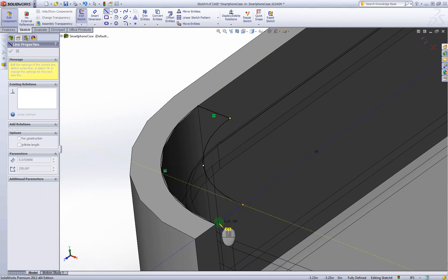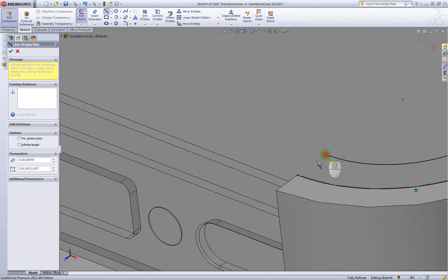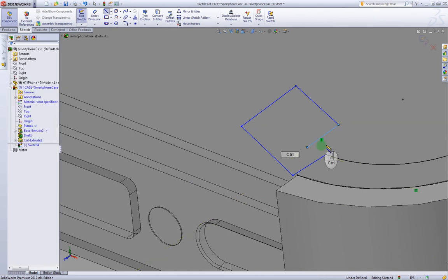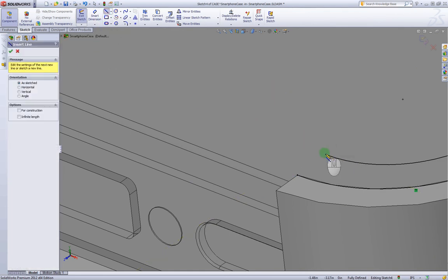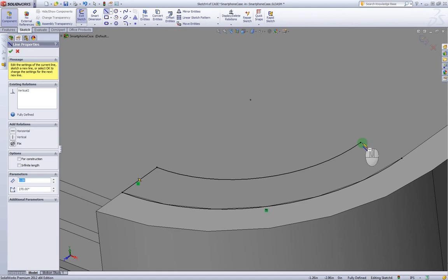Click once, click twice, and if you do it successfully, the line should turn off, meaning if you do it wrong, it's going to want you to keep making lines. I'm going to Control Z here, and if you do it right, you start your line and then you end your line, it just turns off. It's like an auto off because it thinks the line is complete.